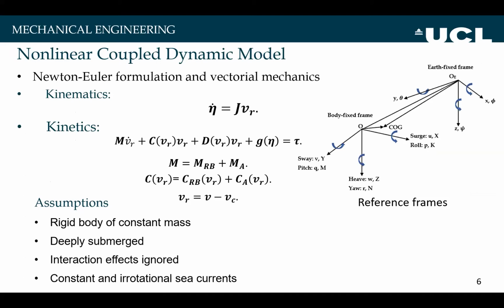So I developed the nonlinear coupled dynamic model using the Newton-Euler formulation and vectorial mechanics. Two reference frames were used, the earth fixed frame and the body fixed frame. The position and orientation of the system were defined in the earth fixed frame, whereas the velocity, forces, and moments were defined in the body fixed frame.